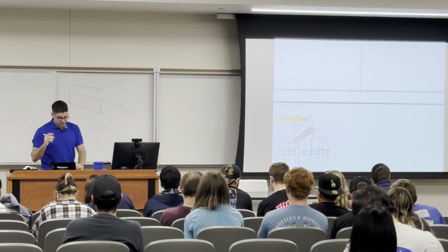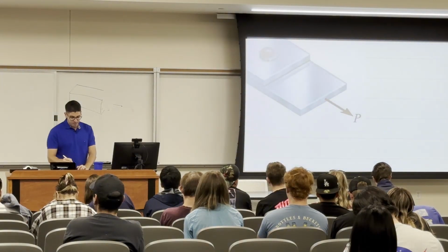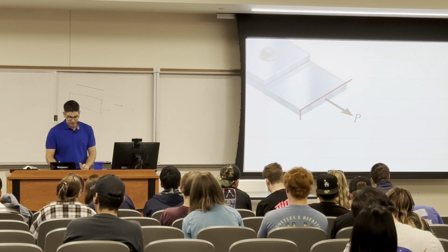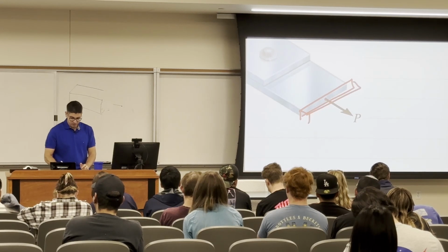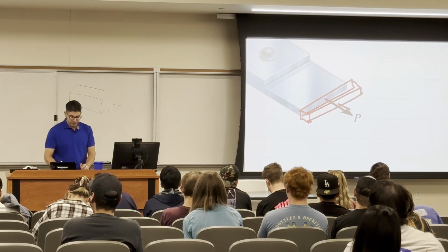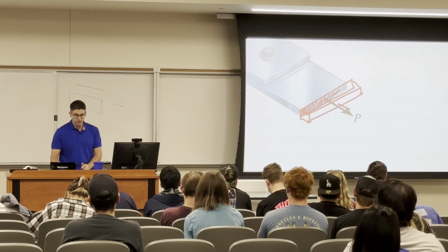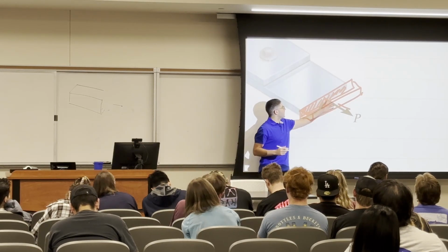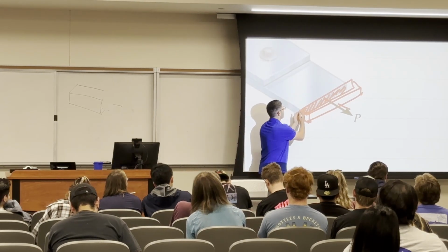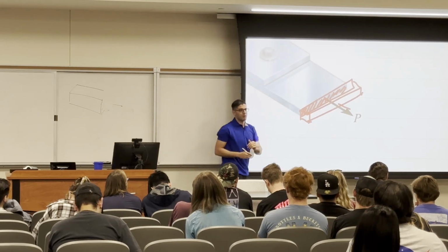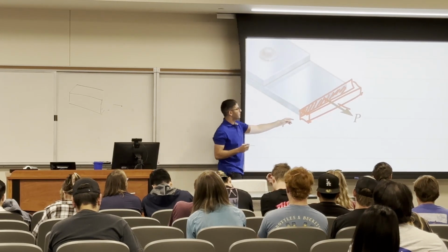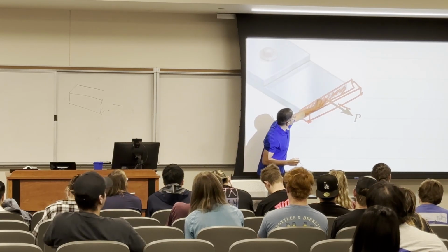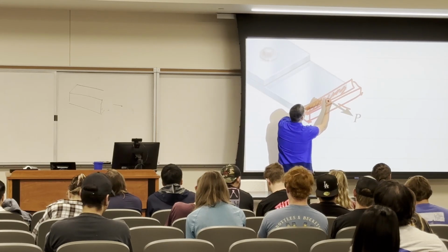So previously, when we applied the force like this, we were exaggerating when we said the force is applied to this point. Instead, what we do in real life is put a thick plate here, and we apply this force on that plate so that the force will be distributed over the whole cross-section. So when you see something like this, it doesn't mean that there is a point load. No. We put a plate so that we can have this force distributed over the whole thing. Or if we have the force being applied as a single load, which is unlikely to happen, at the beginning, yeah, it's going to be point stress, and then it's going to be something like this.